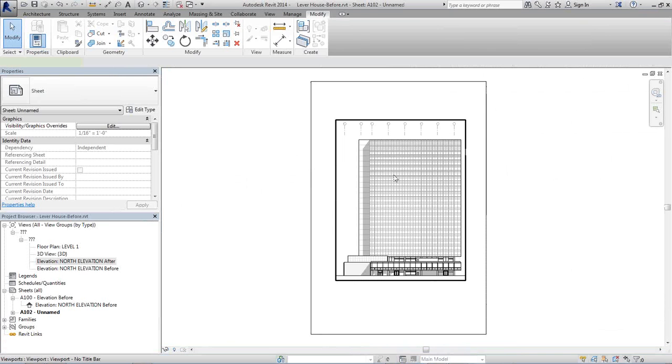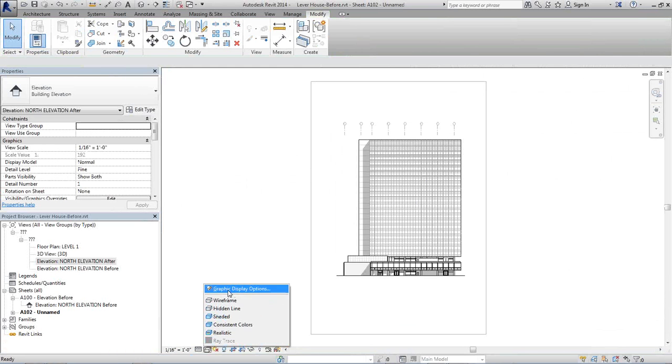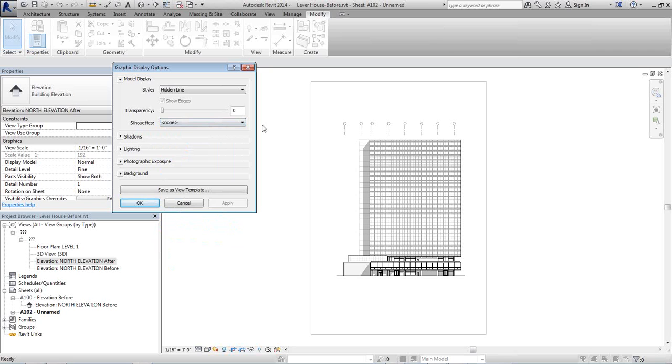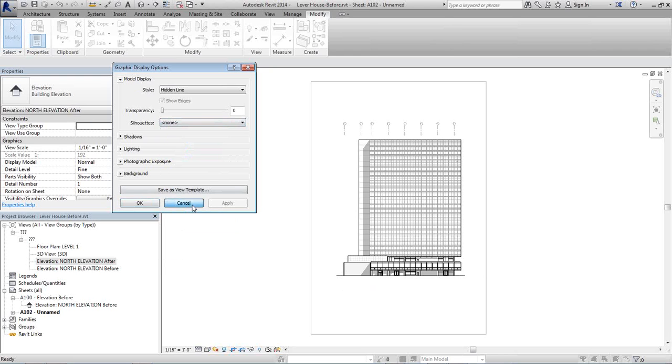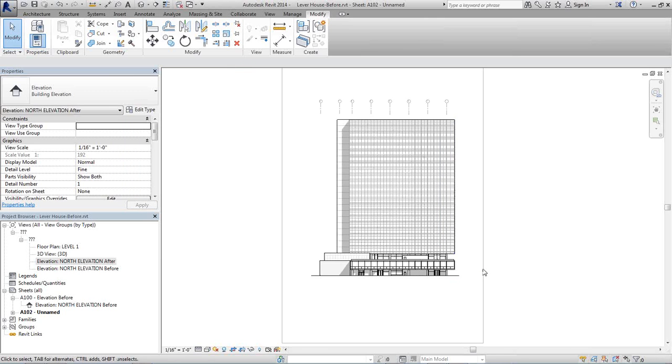It's this crazy tool here called, let me show you, Profile or Silhouettes. And admittedly, I think I used Silhouettes maybe 5 years ago, and it was such a mess. I've never gone back. The idea was that this would somehow take whatever's at the edge of this drawing and give it this line weight. But it's just really clumsy and it doesn't really work very well. So what I've found is that doing this is so much faster, and you can have so much better control over this.